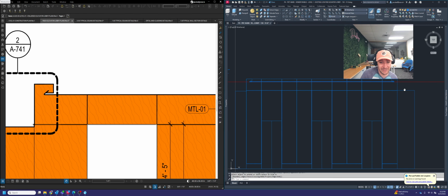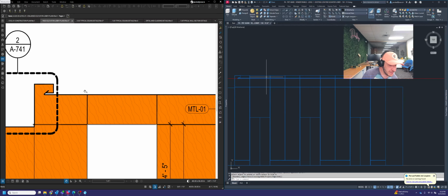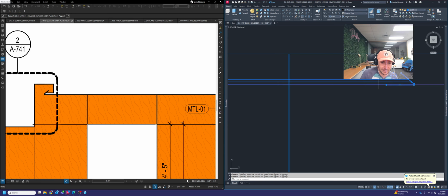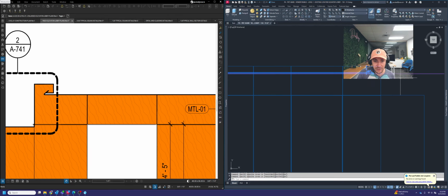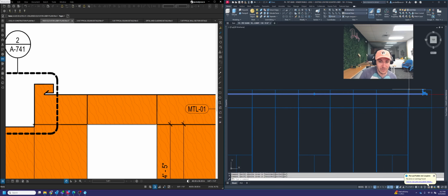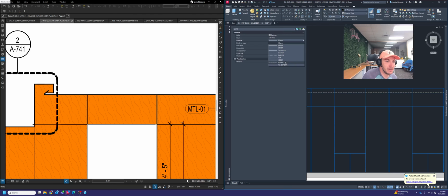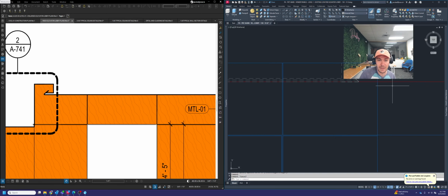Now, one thing that I know because it's not shown here is that because the light pocket and the ceiling are all by others, what I would like to do first things first is put it on the existing layer because that'll be signifying that it is not by onsite. But then for 2, what I would also like to do is make these hidden lines because I want to show our panels beyond without blocking them from view.